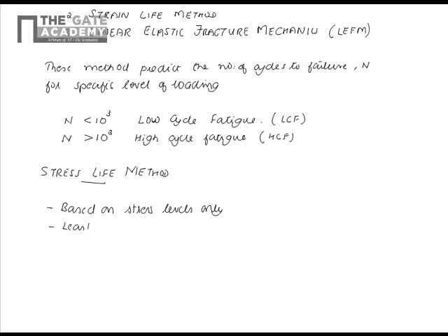It's least accurate especially for low cycle fatigue, because in low cycle fatigue the stress levels are very high, so plastic deformation of the material takes place, and this is not considered in the stress life method. Therefore this method is less accurate for low cycle fatigue components, and this method is easiest to implement for a wide range of design applications.